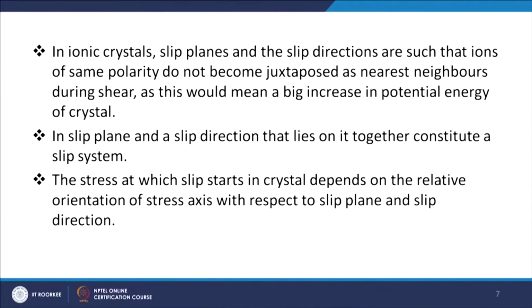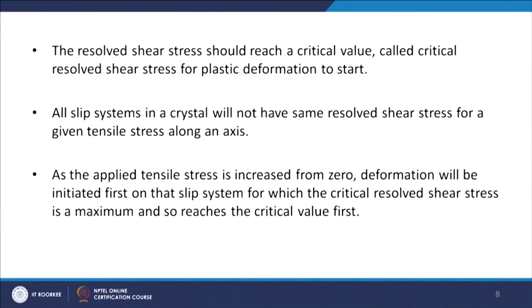So, if you come to the presentation here: the stress at which slip starts in a crystal depends on the relative orientation of the stress axis with respect to the slip plane and slip direction. What we have seen is that we have different planes inclined at different angles, so the slip systems in the crystal will not have the same resolved shear stress for a given tensile stress along the axis.